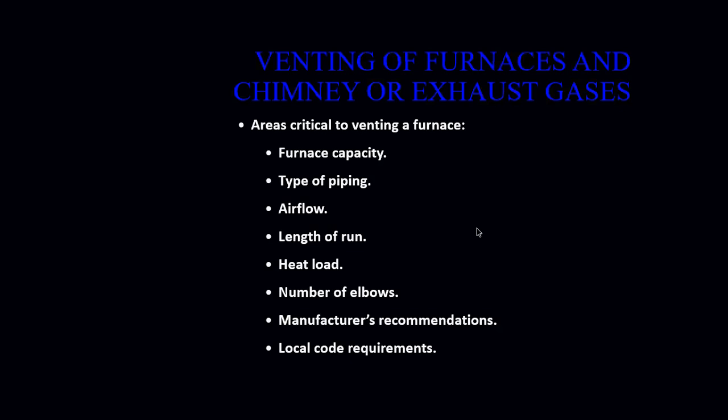Also, following the manufacturer's recommendations is really critical, as it affects how the furnace vents. Okay, those YouTube certified individuals out there who just want to try to do things on their own may affect the efficiency and the venting capacity of a furnace. And obviously, if you do not follow your local code and the international mechanical and NFPA fuel gas codes, that's also going to affect the way a furnace operates.